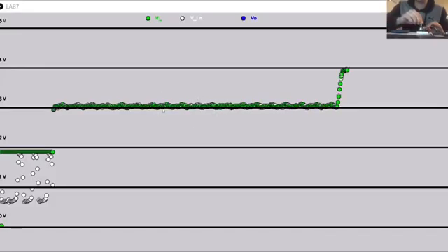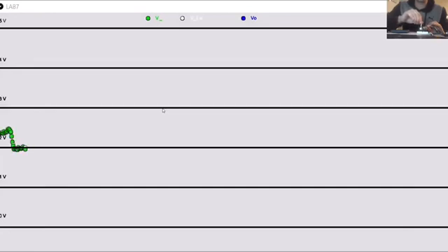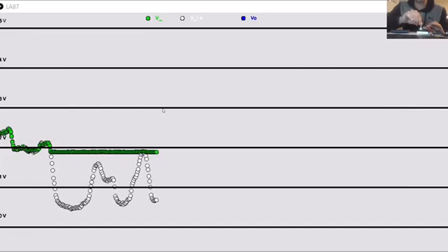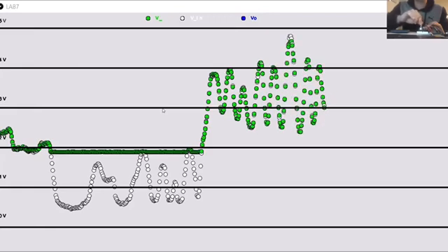Here you can see that all the values mirror together, all the voltage readings mirror together, the V minus, Vin, and the Vout. However, when I go lower to approximately 1.9, the V minus and Vout do not follow the Vin. This is due to the saturation of the op amp. But between 1.9 and 5, all the values are the same, and this is due to the fact that the gain for the system in this case is 1.